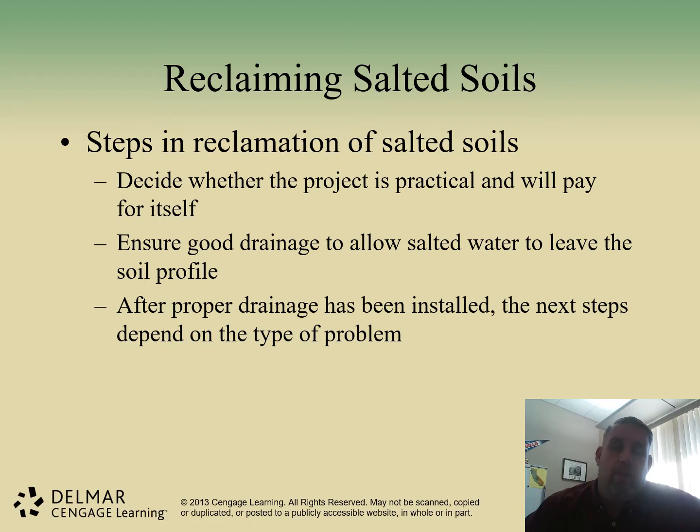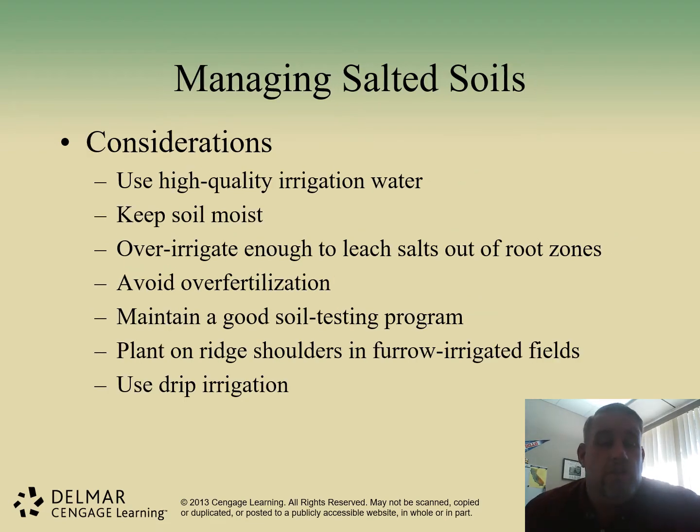Basically, when you're reclaiming these salted soils, you're going to flush or leach these salts through the soil. So you are going to use a higher quality irrigation water. This is pretty prevalent in the reclaimed water industry. If you are watering with reclaimed water, it tends to be higher in TDS or sodium than your potable water, and these solids can be built up within the soil.